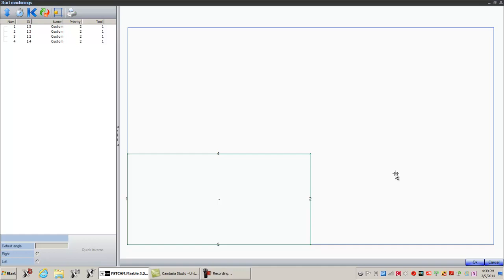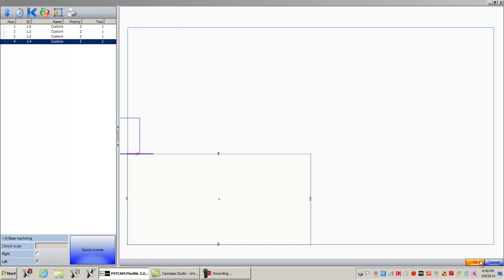So again, if I had 5 parts on here, I'd be cutting all the x-axis, all the y-axis lines, then all the x-axis lines. I'm not going to be turning the c-axis constantly. Furthermore, this set default cut directions will make sure that the water is spraying backwards. See the tail here? That would be the direction of the water, not coming out at me. See, the water's going backwards, towards the back of the machine. Okay? All right, let's hit OK.